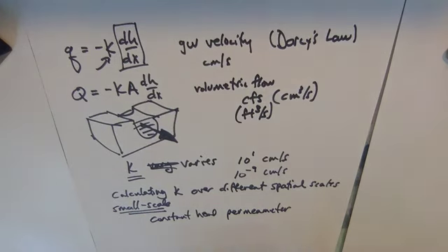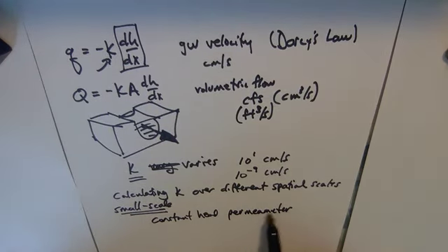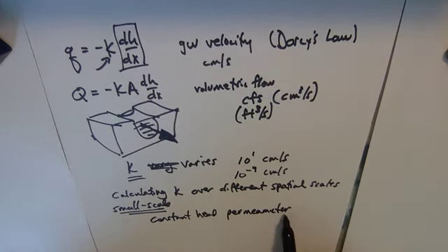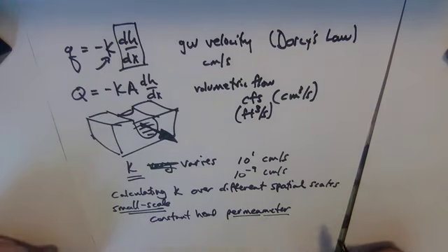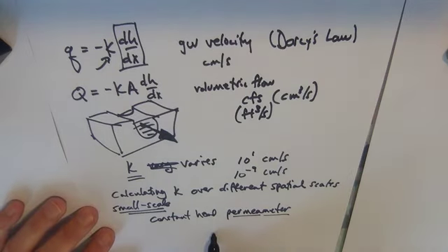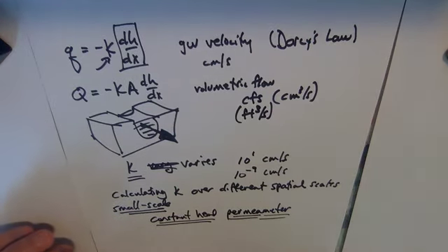A meter is an instrument that measures something. So a permeameter is measuring the permeability, which is basically another way to say hydraulic conductivity, of something. And the way that we're doing it is we're creating an apparatus that keeps a constant hydraulic head, right?